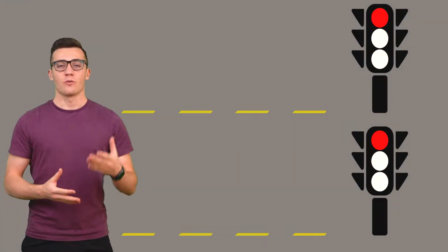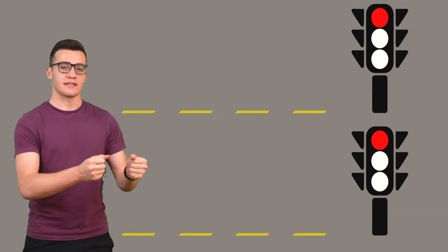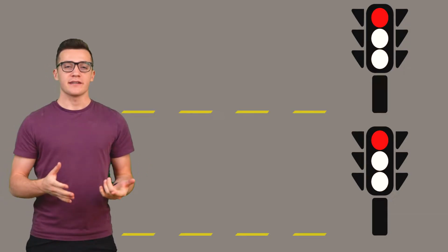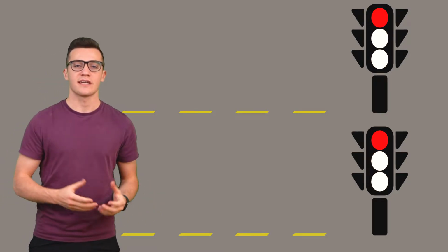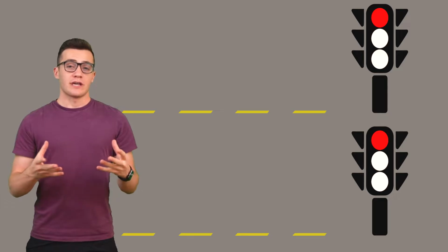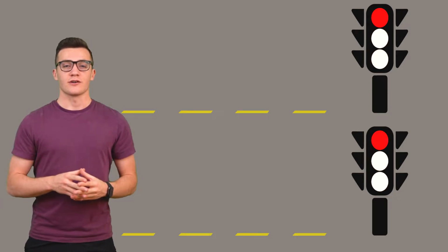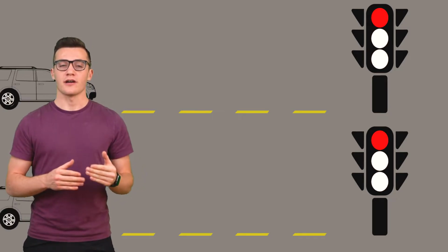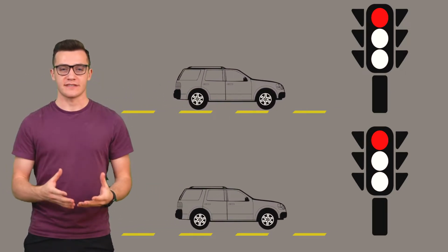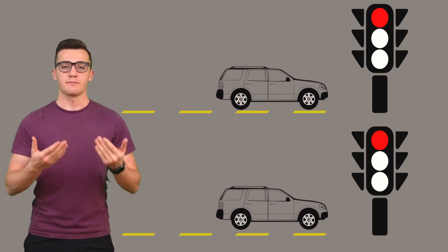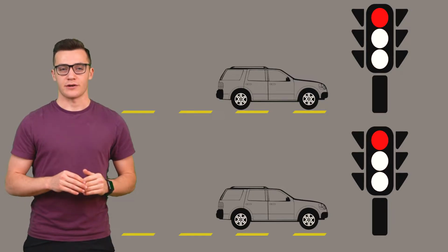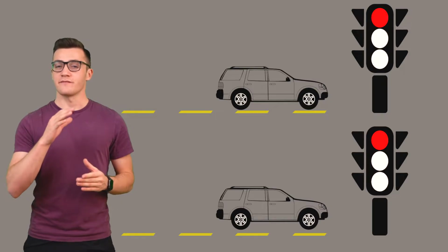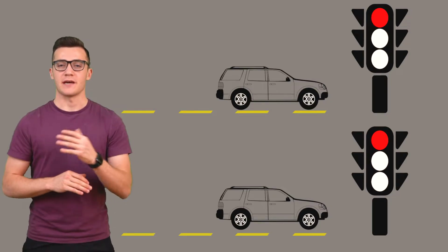Well, to do this, we do the same things your bad driver friend does. While you might brake evenly and consistently as you approach a stoplight, your friend can get the same result by pumping the brakes fully on and then fully off of them until they reach the light. So if you pitted the two of you against each other, it wouldn't be comfortable to be in your friend's car, but in both cases, the end result is the same. You're both stopped at the light and you both stopped in the same amount of time. And this is because your average braking deceleration is the same. And this is a very important concept to understand for PWM.